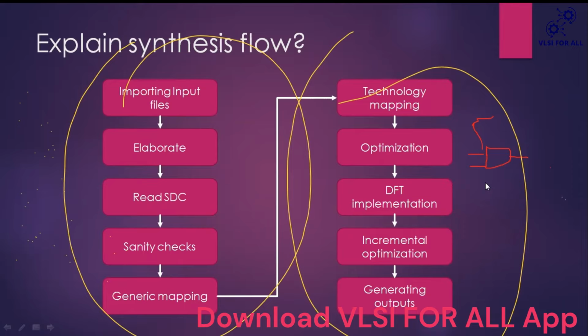During testing after manufacture, if I apply triple one, I have to get the same triple one at the output also. If instead of 111 it generates 101, that is an issue that happened in some flip flop. That's how they identify which flip flop was manufactured properly or not.